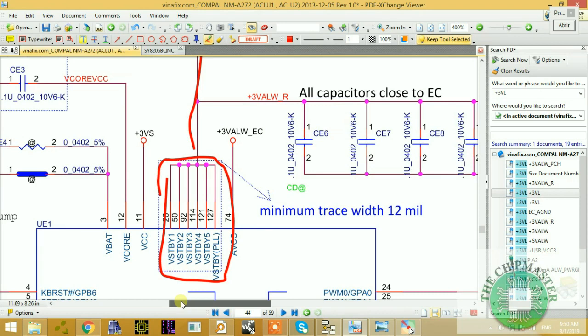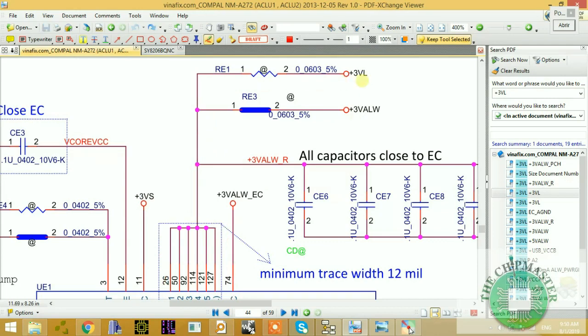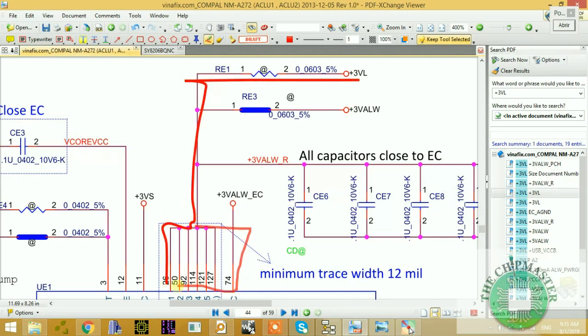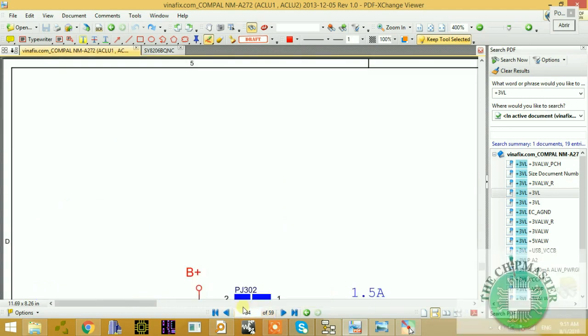Right, so this is the standby. Next, what's the next working condition? Where is it coming from? Alright, so this is coming from our linear voltage. Remember, this is linear voltage, not PWM. This is a PWM voltage. This voltage has not been produced as yet. Remember that. So it needs linear voltage in order to power the IO controller first, because linear is critical, that is needed to power the EC, so the EC can get its working conditions up and running. Alright, so let's go back to page 54, I believe.